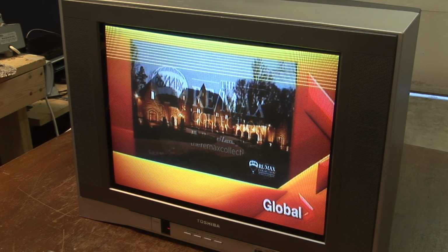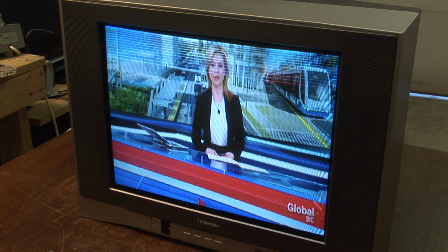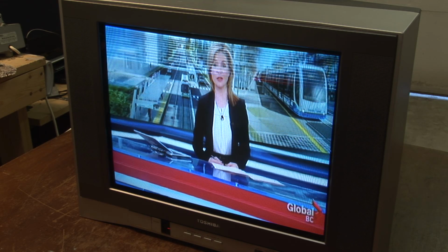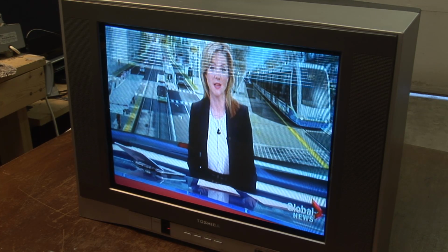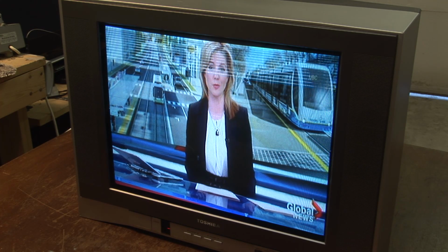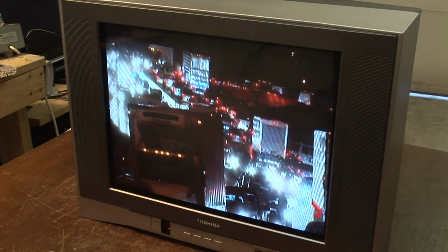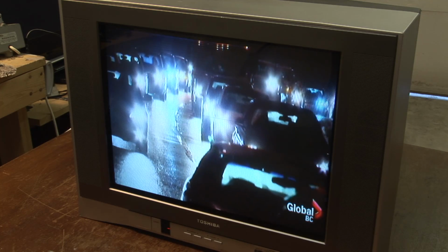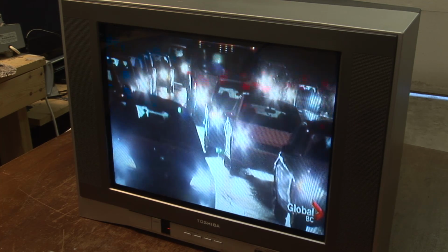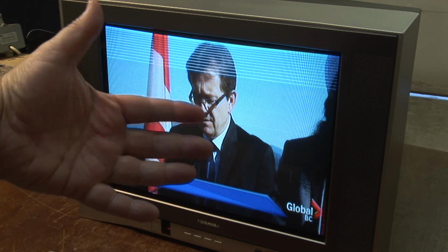It goes back to the analog days of VHS tape and analog cameras that read out, basically Vidicon cameras that read out one line at a time. You would have what was called field slippage. So movement that occurred between one frame and the next could cause jaggy lines. And when people saw the difference between a 480 progressive from a DVD, which was taken off a film source, and a 480i from a tube-based camera that was scanning line by line, there was a noticeable difference. In the digital world, it's not really that big a deal because the CCD is capturing all 1080 lines at the same point in time.